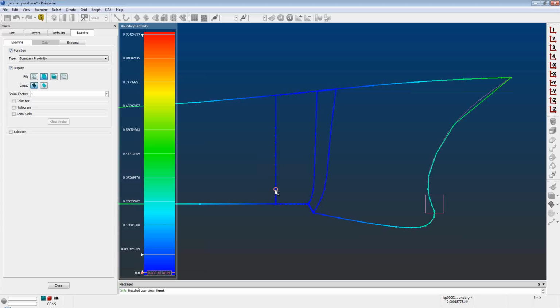And that's where I go to get a general feel for what my gap size is. Then when I go to enter a tolerance value, I want to set a value a little bit larger than that. You don't want it to be two orders of magnitude larger, just enough to close up the gap. Otherwise, similar to the last question, you'll get unwanted results. You just want to use a tolerance that's slightly larger than the gaps in your model.